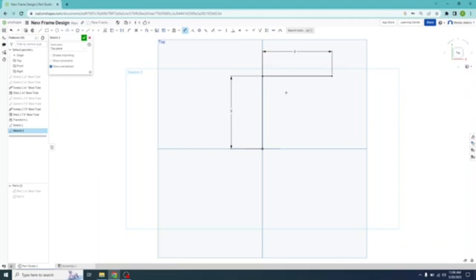But before we do, let's go in and we're going to use this sketch fillet tool. This is going to help us set the radius for the bend because we don't want a hard right angle. So we're going to come down here. We're going to select this line, and we're going to select this line by left clicking both when they highlight, and then we're going to draw that out. So let's go 1/2 inch, and we want to set that at 0.5. So we'll go 0.5, hit enter, there we go.